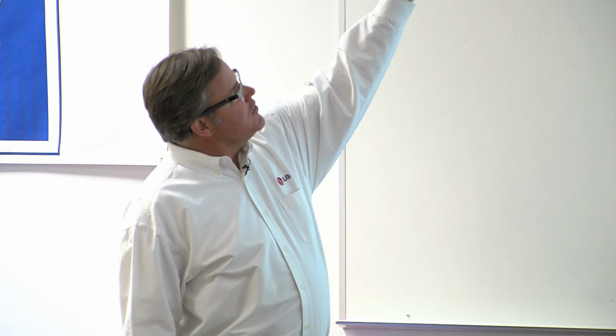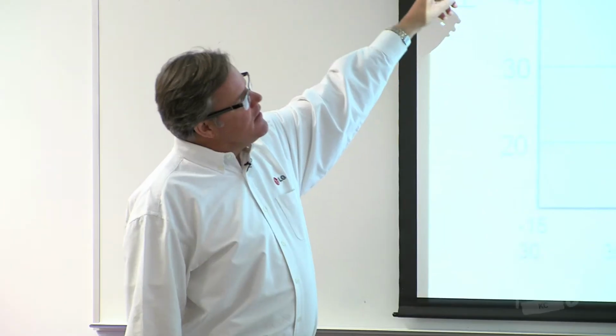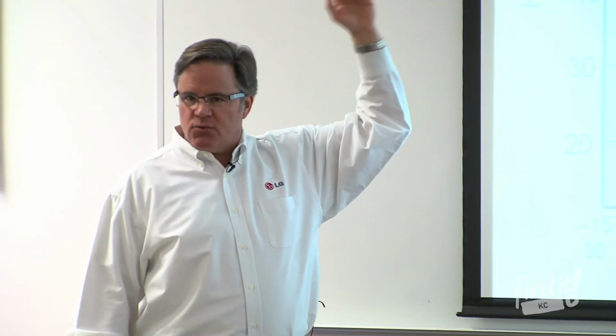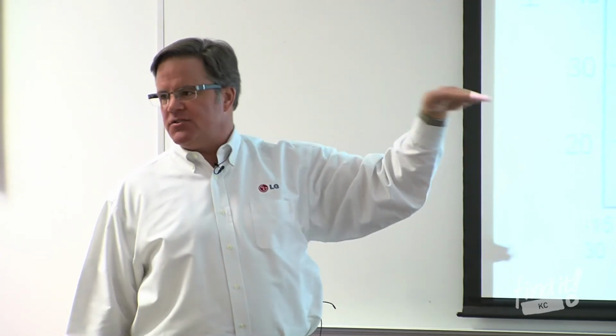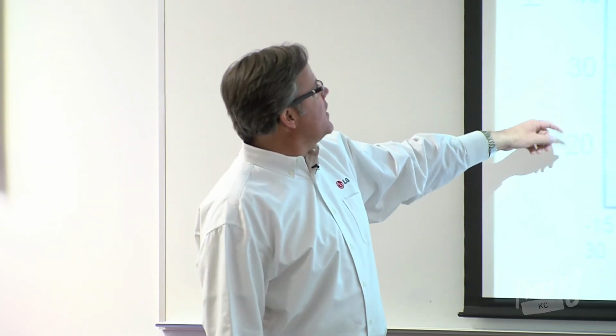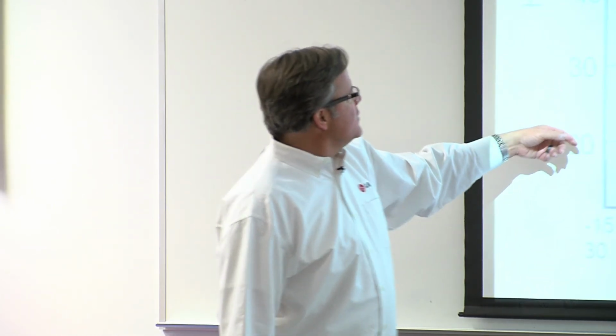Or, I'm sorry, this one's out of the catalogs. My bad. The next one is out of each manufacturer's catalog. What their catalog says, how many BTUs they can give you at different heating points, okay? So this is how much heating capacity in tons can a 6-ton unit give at these different temperatures.